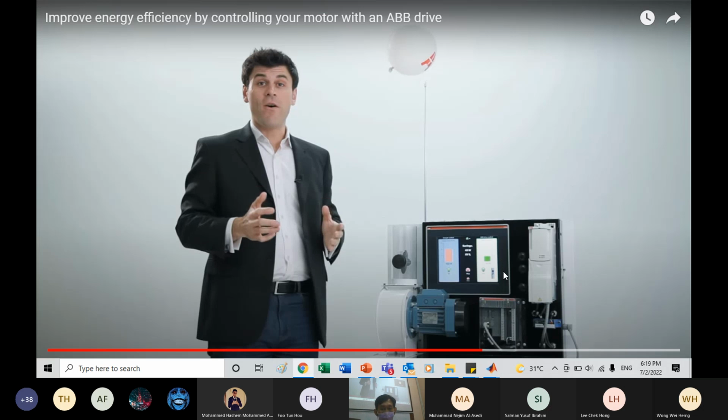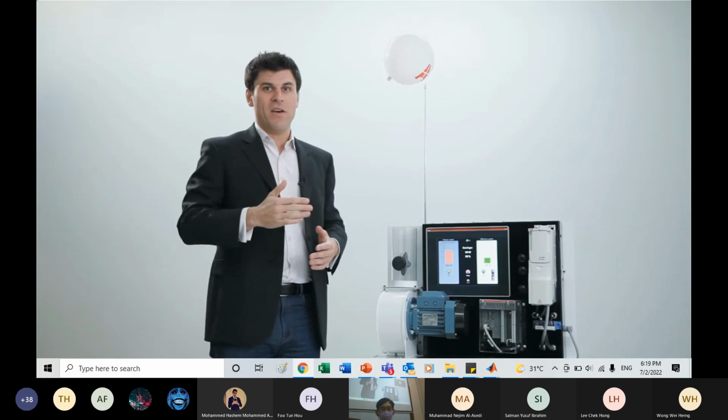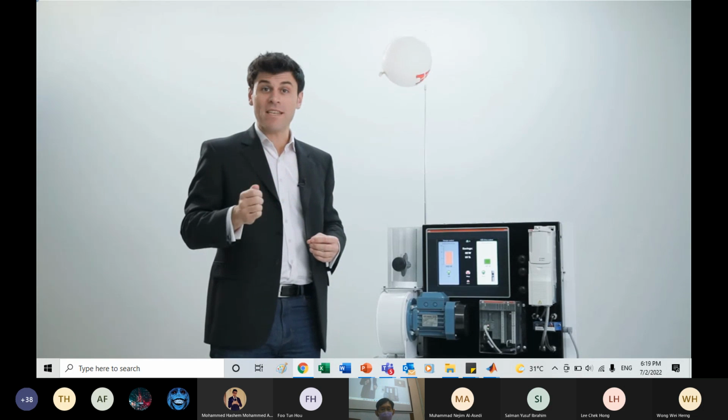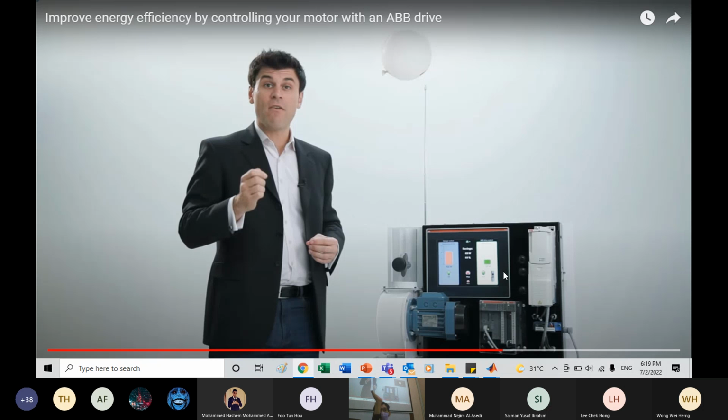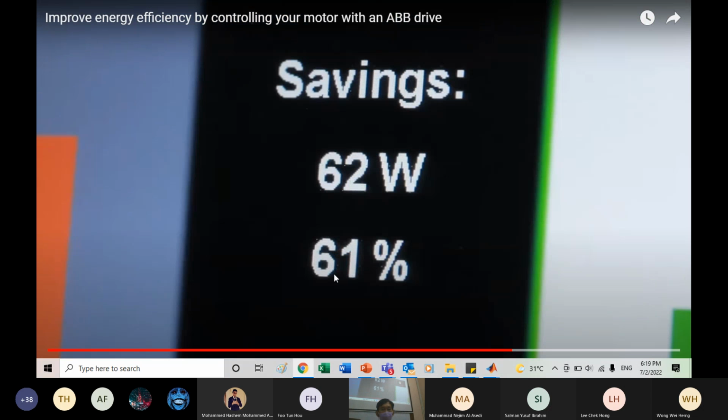Okay, so the airflow is the same. Firstly, there's a lot less noise, but more importantly, you use a variable speed drive, you control the speed, lower power, lower noise. Remember, the aircon is very noisy, right? At night, wow, maximum. If you use a damper, okay. So the hotel, there's a power saving of around 60%. As you can see, the variable speed.